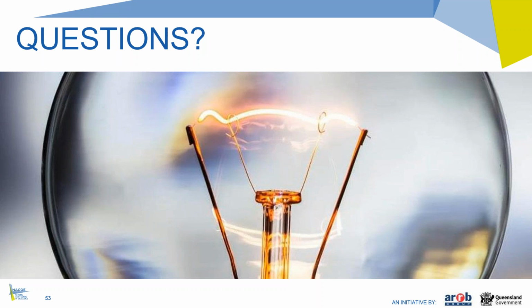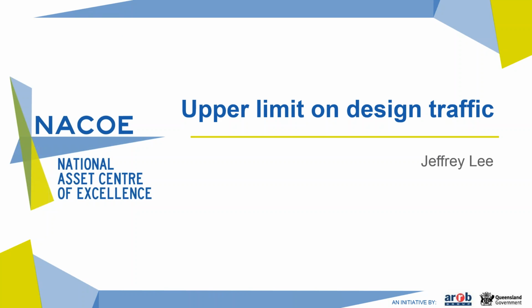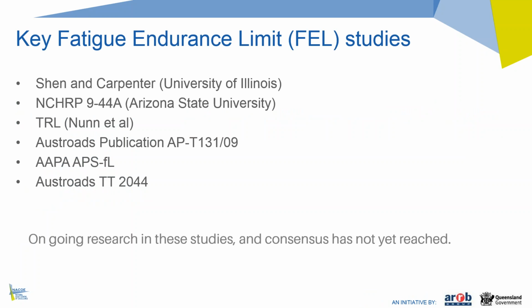Thank you, Angela, and good afternoon, everyone. Just to clarify, we are discussing putting an upper limit on design traffic in Queensland, and mainly this is for a freeway type of situation. Whenever we discuss putting a cap on the current asphalt thickness, inevitably the concept of the fatigue endurance limit comes into play.